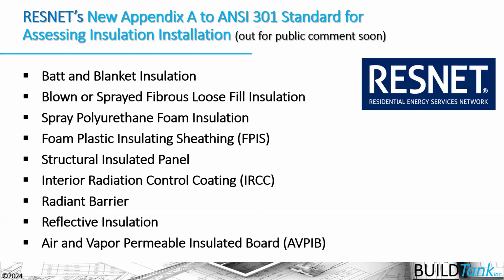And what they're ultimately going to do is break down these different insulation materials and tell you how to look at it and how to assess it, to demonstrate that it's been installed properly so that it can be energy modeled with its rated R value. If it's properly installed, it can be rated and modeled with its rated R value, which means that it's been installed according to the code. Ultimately, we're going to get better alignment between the energy rating index, energy modeling, and the code requirements for modeling.